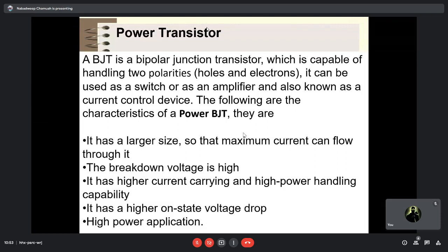This is something different. I am asking why it is called voltage control. Because the current flowing in the drain is controlled by the voltage actually. Which voltage? That is fine, you are applying voltage at gate-source and also drain-source. Which voltage will control the current flowing through the channel? Gate voltage, yeah.